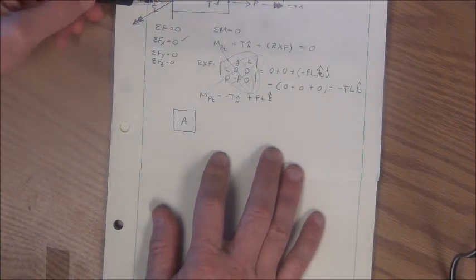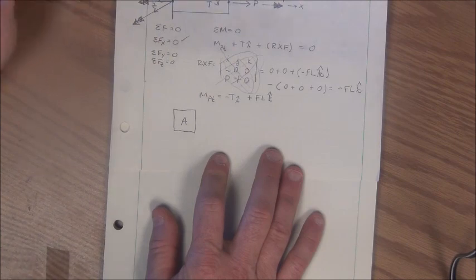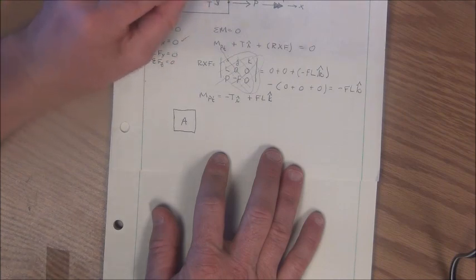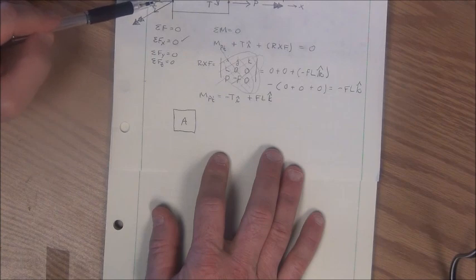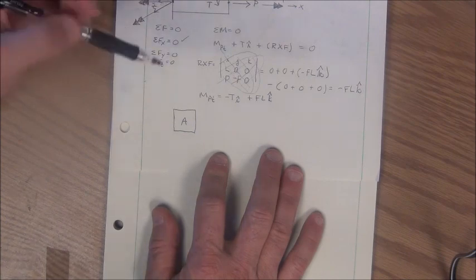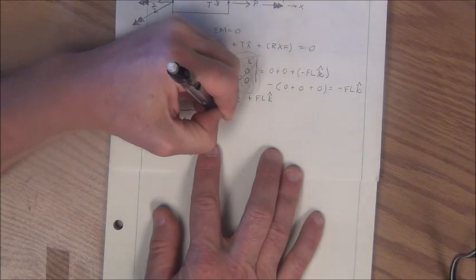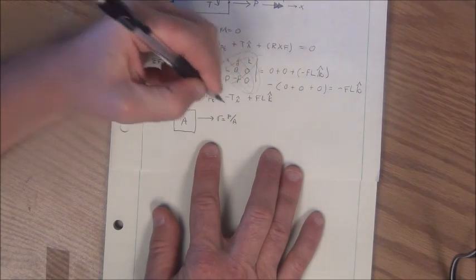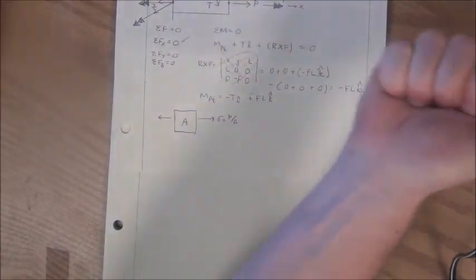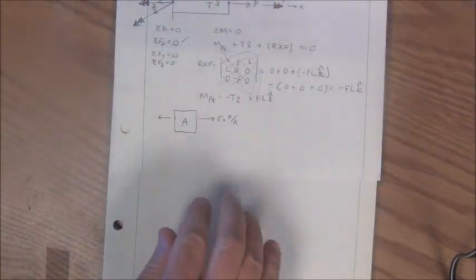So starting off with my P load, or my axial load, it's not a moment, so there's no way it can do MC over I. It's not a torque, so it can't do TC over J. And it's a normal force. It's not a shear force, so it can't be a V. So there's no way that this normal load P, which is perpendicular to the cut plane of interest, can be anything but sigma equals P over A. So I'll now draw sigma equals P over A on my stress element. And it's acting in tension. P's trying to pull my element apart like this.